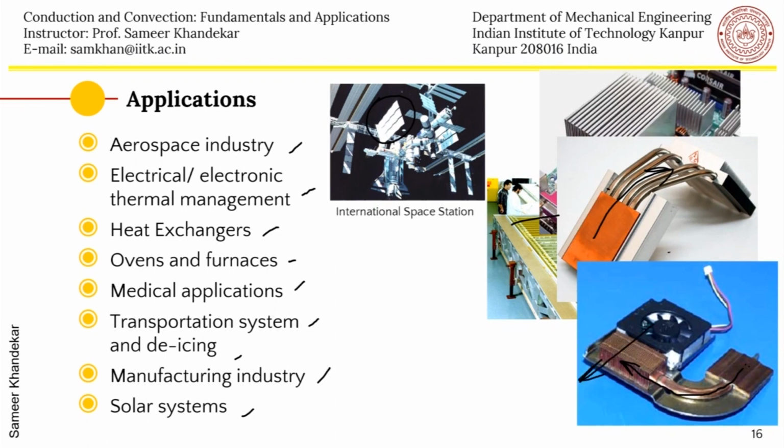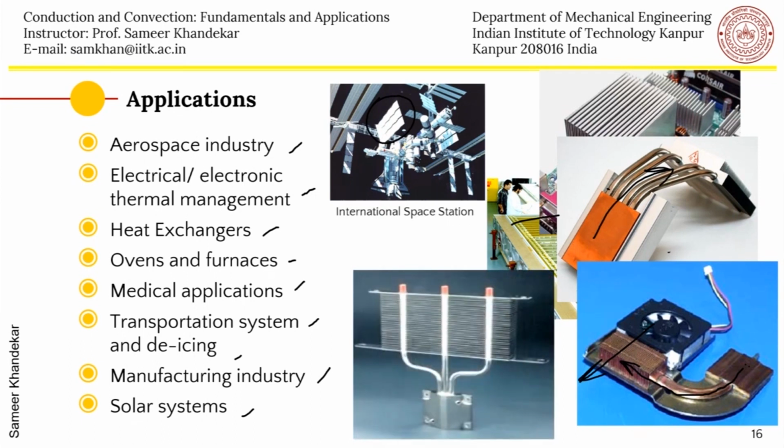Naturally there is air flowing over here, so the area outside is much larger, and the heat transfer coefficient here is high. So the H1 is high and A1 is small, and here the H2 is small and A2 is large. In this way heat is transported from location A to location B very efficiently.